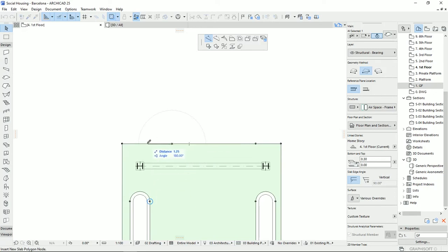I'm going to keep down the shift key and click. Now I can change something on this edge. Here we can draw a curved edge for the slab tool, and we can just set in some values for the radius. And then here we can draw a circular edge by using this handle. For example, if I want this circle here to be perpendicular to this side, I can do it easily like that with the help of guidelines.